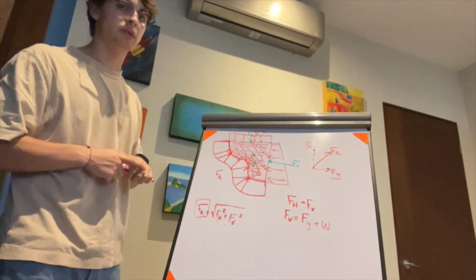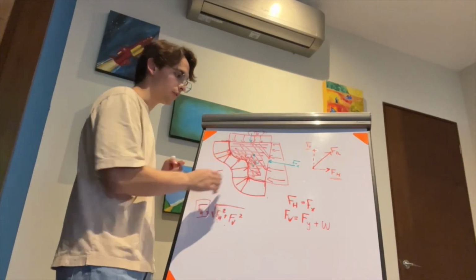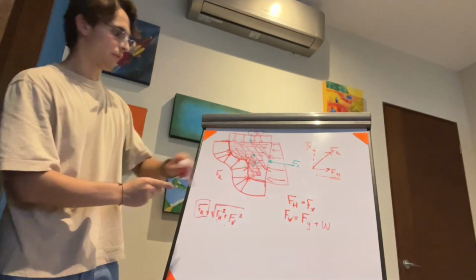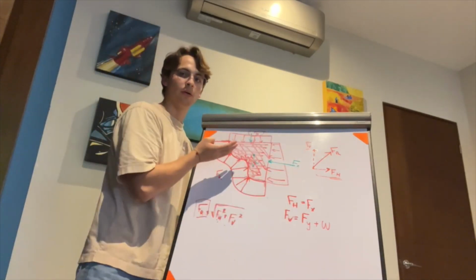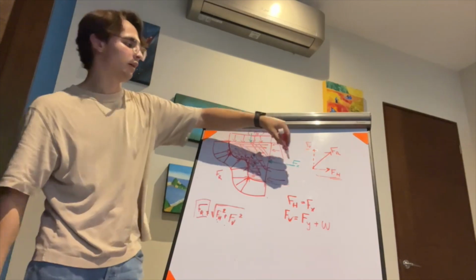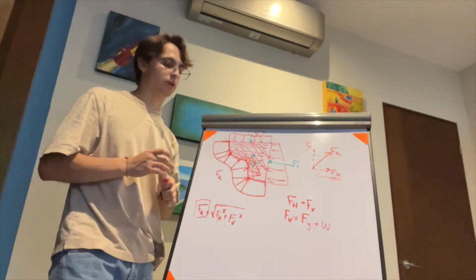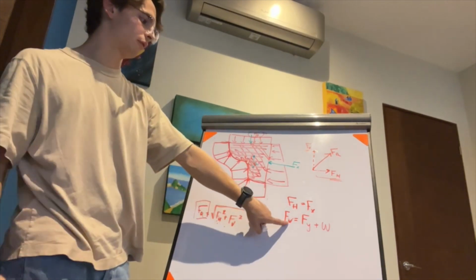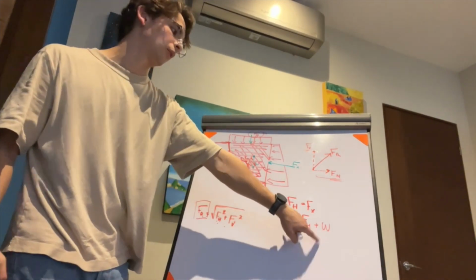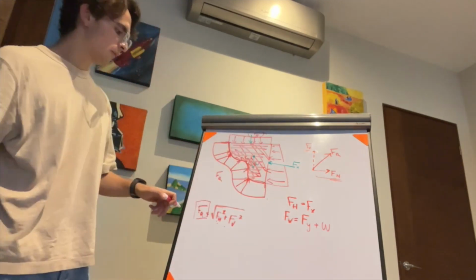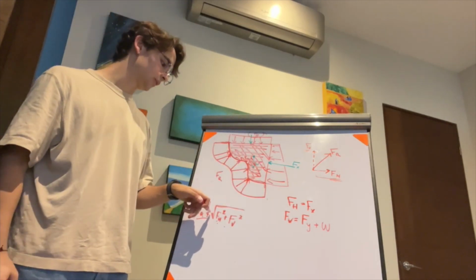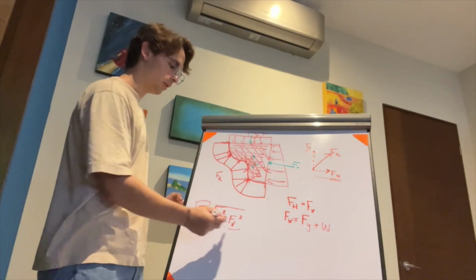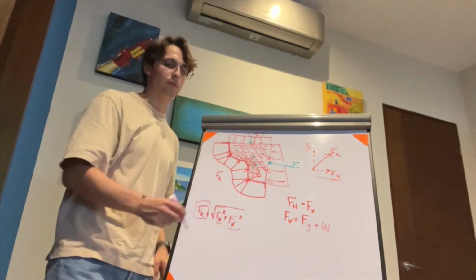But essentially, what we see is that for any given resultant force, you have the resultant force and the components Fh and Fv. Fh would be equal to Fx, the horizontal hydrostatic force, which would eventually need to cancel out each other. And for the vertical force, you have Fy and the weight of the fluid. For the magnitude of Fr, you use the Pythagorean theorem of Fh and Fv, which is the square root of Fh squared plus Fv squared.